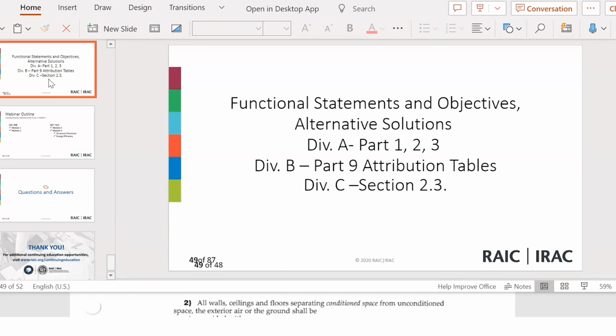You're welcome. So we know what the systems and the materials, assemblies and components associated with thermal designs are. We know where to look for heat transfer and thermal performance. We know that the code will send us back to some parts in Part 3, for example for the design of firewalls. When we're looking at the design of plumbing facilities, we go back to Part 7, and we're looking at some of the occupancies for 3.7.